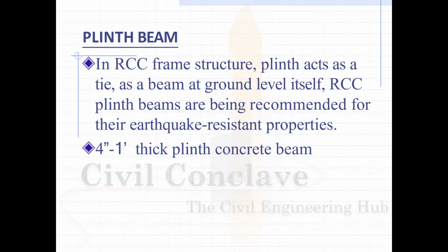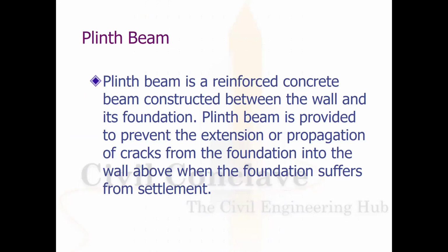Plinth beam. In the frame structure, the plinth beam acts as a tie, as a beam at ground level itself. RCC plinth beams are recommended for their earthquake resistance property. A 4 inch to 1 foot thick beam is the usual plinth beam size. A plinth beam is a reinforced concrete beam constructed between the wall and its foundation.